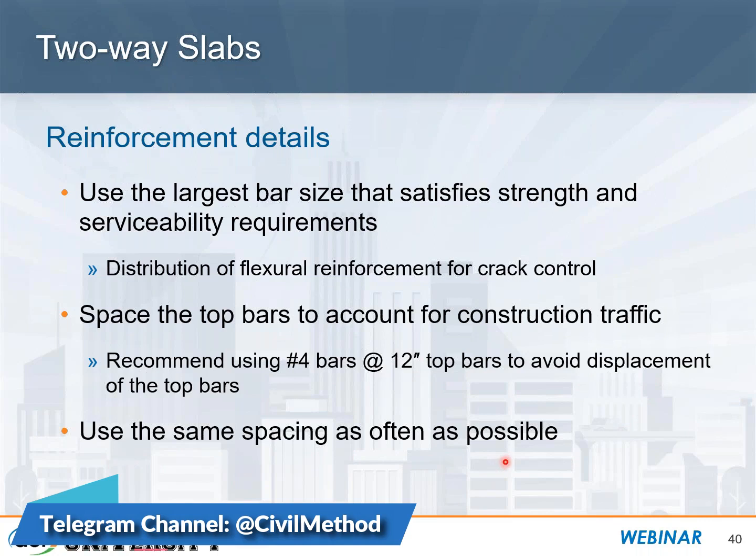So for our middle strips, there's no reason why we shouldn't be using just a minimum reinforcement at close to maximum spacing. Also, in the column strips, using the same bar size and the same spacing as often as possible.